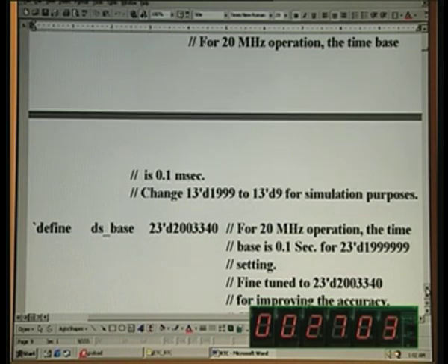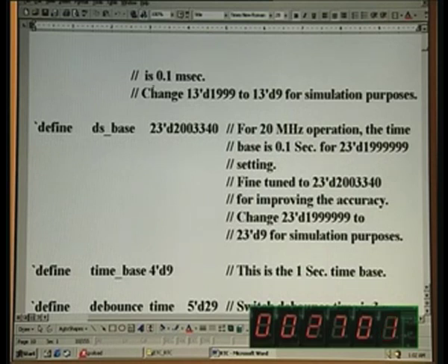and otherwise it will be an impractical task for you to run the test bench, because we are no longer dealing with a small number, but almost astronomical numbers, because hours, minutes, seconds, and again from 20 megahertz onwards we have to start counting. That means 20 million count, then followed by 60 for seconds, 60 for minutes, and then 24 hours. You see it has already skyrocketed to astronomical heights. Okay. So writing an elaborate test bench will be a very difficult affair, and we need another definition.